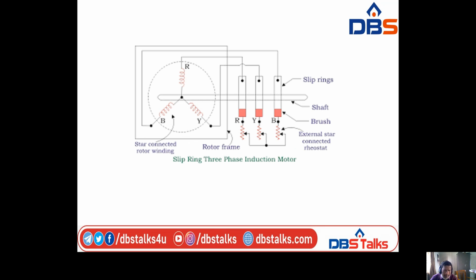Look at the figure clearly. The stator may be connected star or delta, depending upon the rotor construction. Suppose the rotor is star, the stator is star or delta, whatever it may be. Stator put in star may be more useful. So star connected rotor conductors, R phase, Y phase, B phase. So the ends of the 3 phases may be connected to the 3 slip rings. Look at the figure clearly.